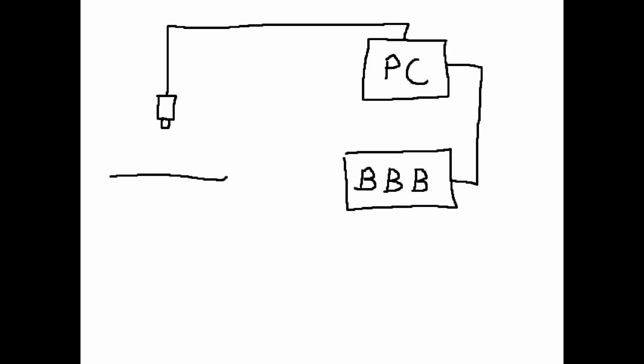The PRUs are absolutely real-time. When they are set running, they execute in parallel with the CPU of the Beaglebone Black, and there is no swapping in and out of memory or pausing their execution. The TILO project assembly code running in the first PRU is designed to accept up to 6 frequency values and output a guaranteed steady waveform for each on an I/O pin.